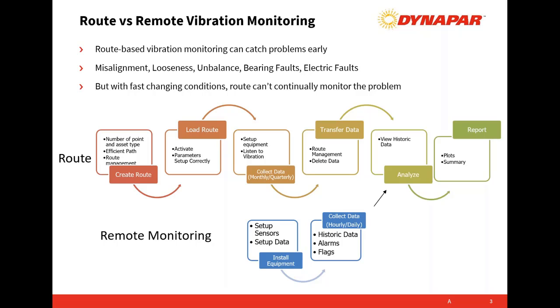So, but the bottom line is, with remote monitoring, you can set up the sensors, install them in the equipment, and then on a periodic basis, hourly, daily, even minute by minute if necessary if you're troubleshooting, the data can be read in, and then a remote technician or a technician locally anywhere in the building can take a look at that data. The analogy I like to use is, instead of making a house call, which how many doctors these days make house calls, you have remote telemedicine, the ability to have your data analyzed.